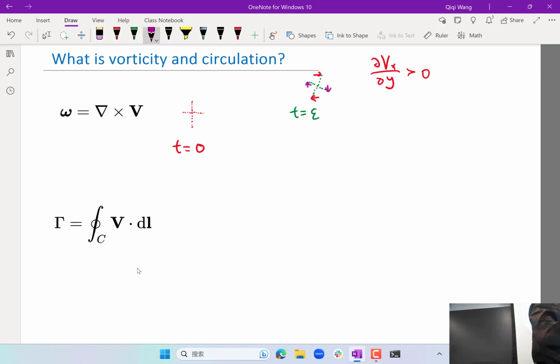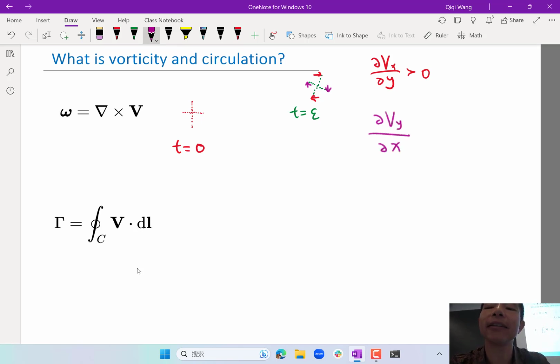According to the x direction, the y velocity has a negative partial derivative, because the higher x values to the right are more negative. That's right. So there is a negative partial derivative of y velocity. We are drawing arrows in the y direction, and the more my x is, the less my y velocity is. So that's why we have a negative y velocity gradient.